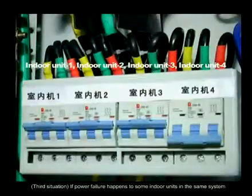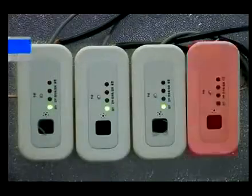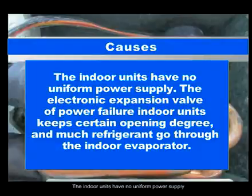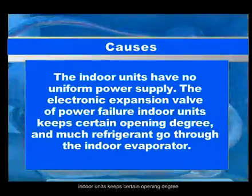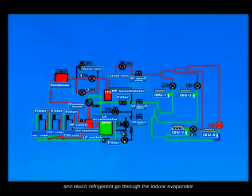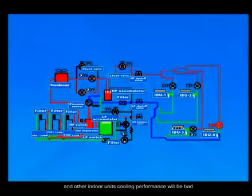Third situation: power failure happens to some indoor units in the same system. Malfunction analysis: the indoor units have no uniform power supply. The electronic expansion valve of the power-failed indoor units keeps a certain opening degree, and much refrigerant goes through the indoor evaporator. Condensing water will appear on the indoor units, and other indoor units' cooling performance will be bad.